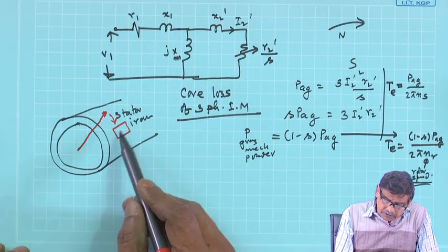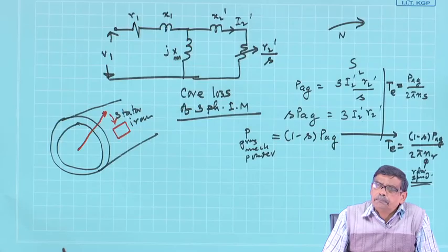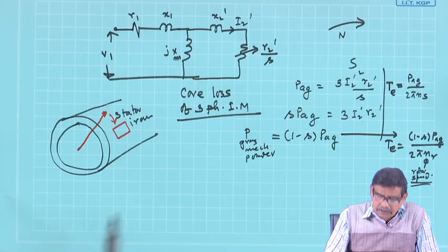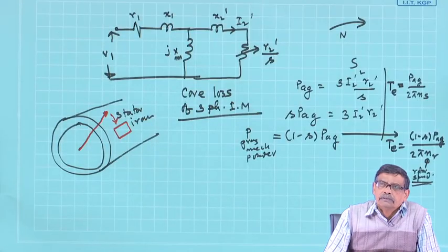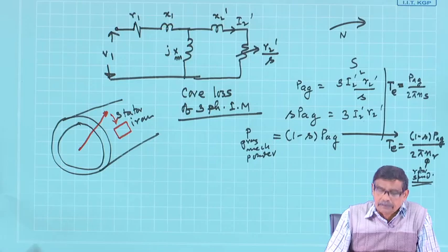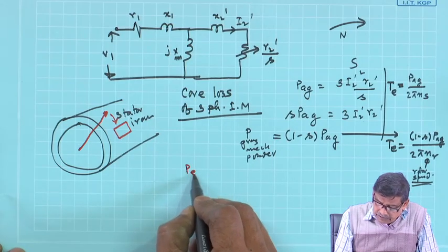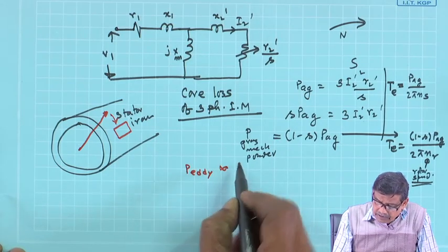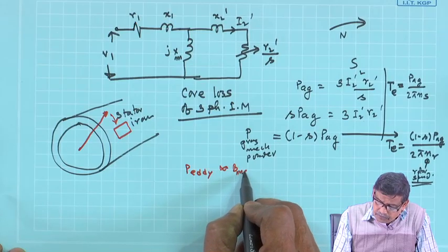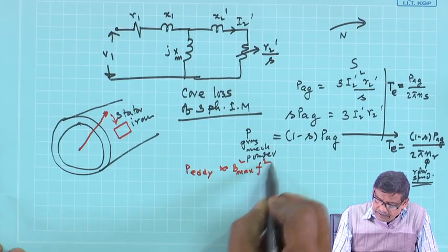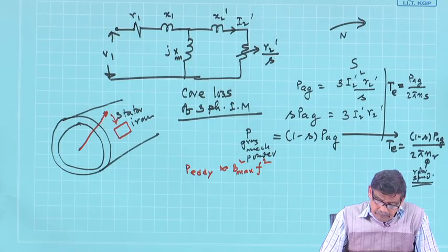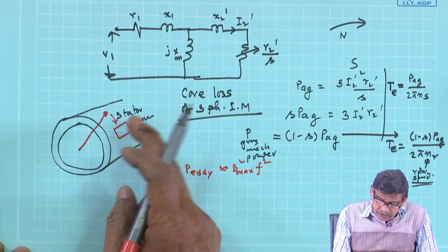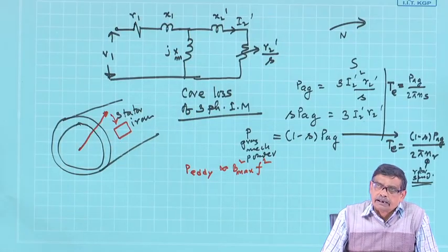This power loss will be proportional to, just like in a transformer, the frequency at which this flux is cut in this loop, that is f squared, and the maximum value of flux density squared. So, eddy current loss, as you know, in a transformer, is proportional to B max squared f squared, like that, per unit volume. So, eddy current loss will take place in the stator iron.